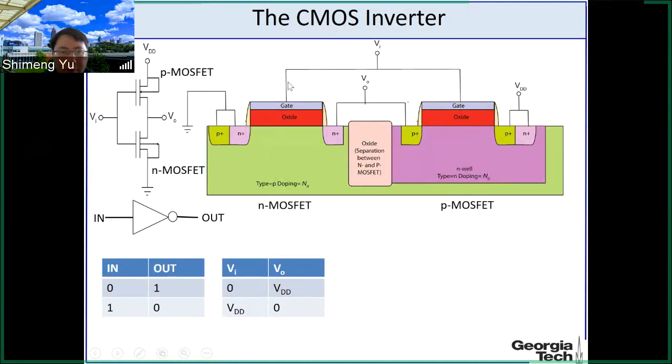Then you have to use some interconnect metals to wire those terminals, like the two gates are connected together. So you need to use this wire here to connect those two gates. And if you recall lecture 2, this is a metal interconnect. We have so many layers of metal interconnect. For those neighboring cells, we just use the lowest level, like metal 1, and make the interconnect between those two gates. And then the drains of the NMOS and PMOS will be collected as an output voltage.